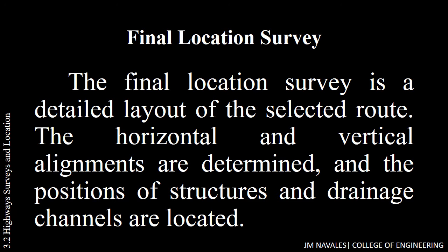And last, for final location survey, the final location survey is a detailed layout of the selected route. The horizontal and vertical alignments are determined, and the positions of structures and drainage channels are located. So therefore, in the final location survey, all the plans in constructing the highway are clearly and firmly finished.